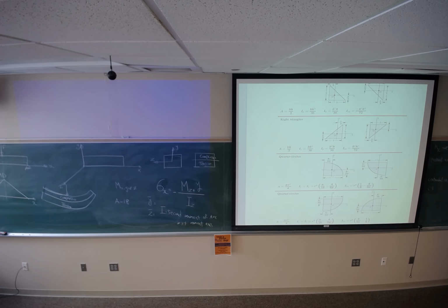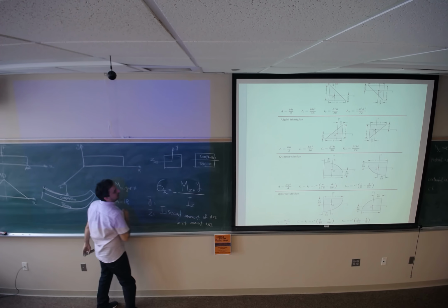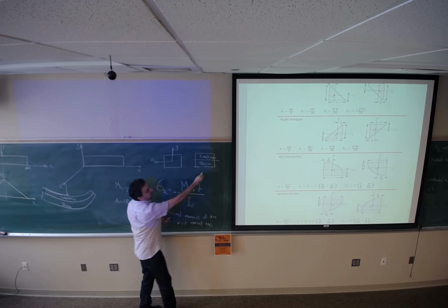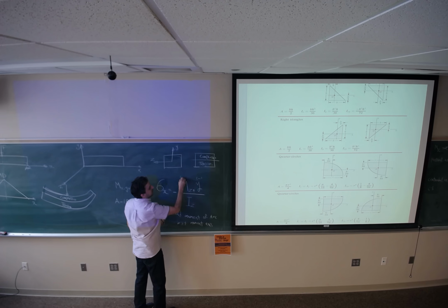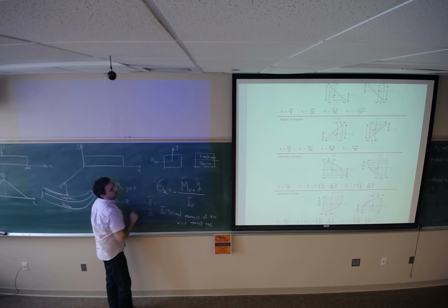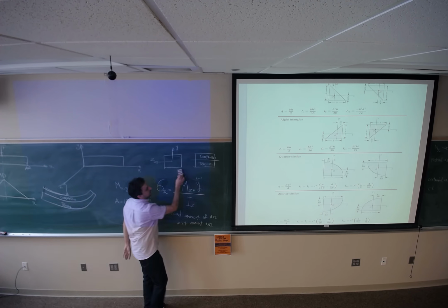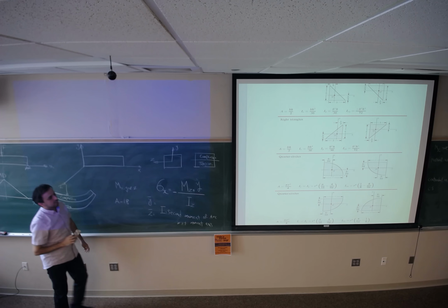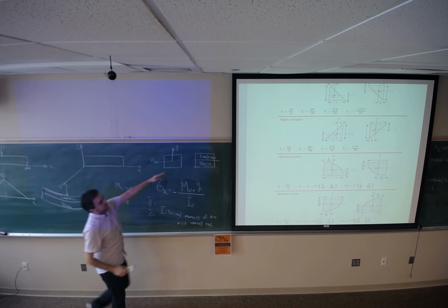So we should get the negative sign for the normal stress. That's the reason I need to put a negative sign here. For any point below this line, y is going to be negative, M is positive. So negative times this negative, you will get positive normal stress, which represents the tensile stress on any point below this line.